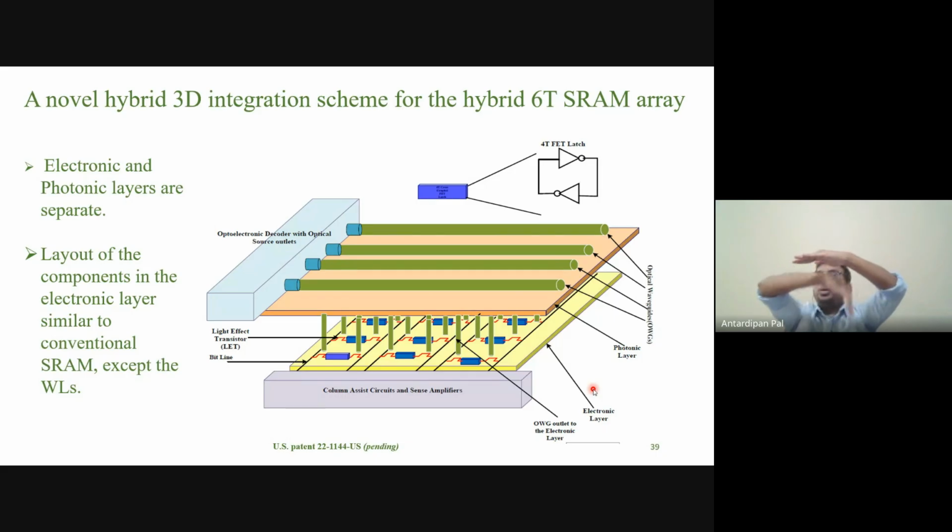As the number of openings increases, there will be some loss at each opening. Coupling loss, or not coupling loss, to be honest. I forget the name. There are some losses, the bend loss, because you have to bend the waveguide. Bend loss at each opening, and the overall loss as light propagates will increase.